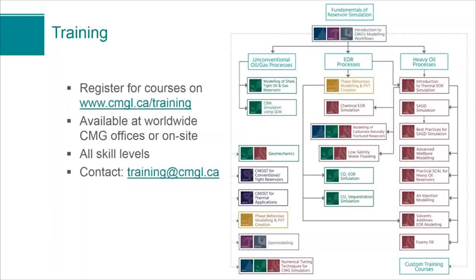I mean, that was actual real lab data, but just because it's real lab data doesn't mean you would actually use that in your real reservoir. If you use that kind of a severe degradation, you would get a lot less incremental oil.